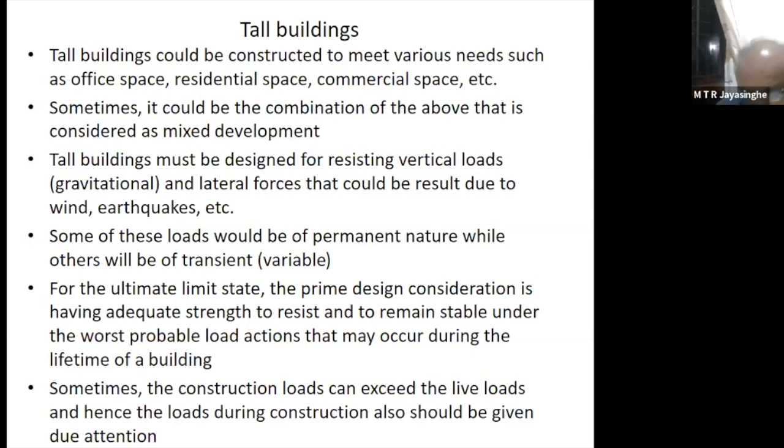So still curing the slabs for at least 7 days, at least until the shuttering of the upper floor comes, so that the lower floor becomes shaded. You have to do it, because our climatic conditions are not conducive for cement to gain strength. You have to look after the concrete.